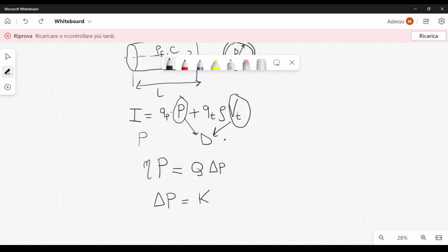So it's not really something very rigorous, but it is possible to estimate this coefficient, and it takes into account the shape of our pipe. Then this decrease in pressure is proportional to the density of the fluid, and it is also inversely proportional to the diameter of the pipe, and it is also proportional to the kinetic energy per unit mass of the fluid, which is the velocity squared, c squared, of the fluid divided by 2, and then it is also proportional to the length of the pipe.